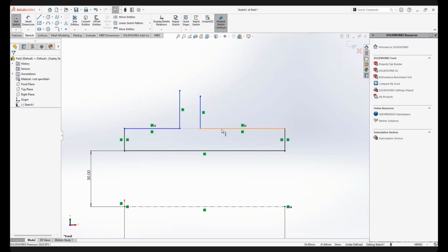Okay. This one and this one, I said we need to set another relation. This one and this one, what else? Yeah, it's collinear then. What other relation? This one and this one, what one more relation that we missed? This line and this line. What is it? Look at the question. Both the right side and the left side have the same length, right? This one and this one must have the same length.